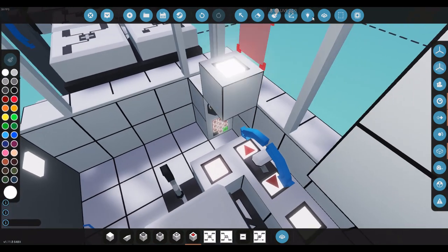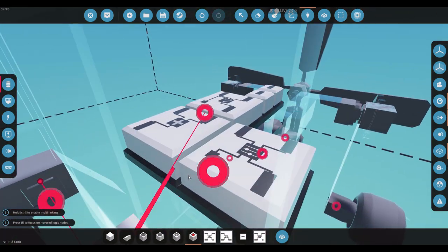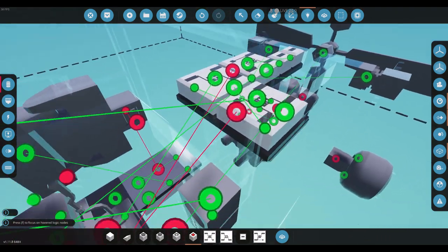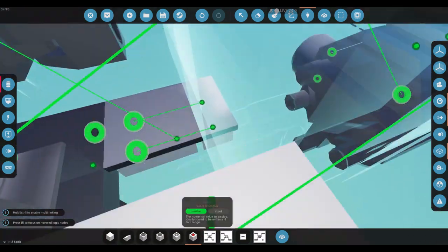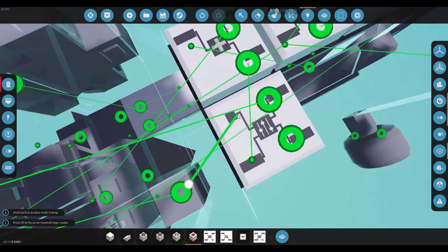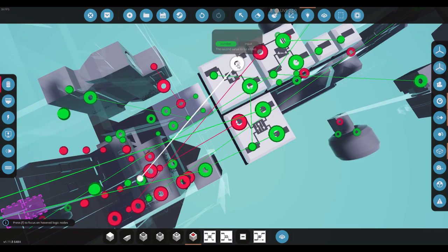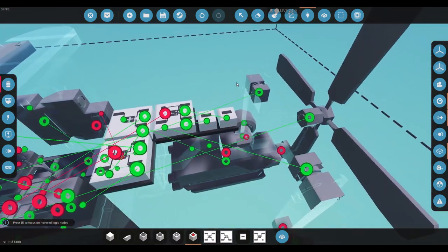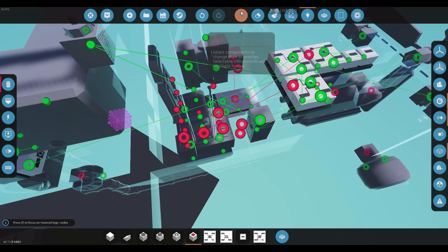Now this is going to be used to control our on and off for our speed hold. So this will come to the PID activation. And now for the set point, we are going to use the keypad. So the keypad we placed is going to be the set point for the PID. So here's the PID set point. So here we go. This is hooked up to that. That's hooked up. Okay, so now let's make sure this gets, oh, and let's tune it really quick.